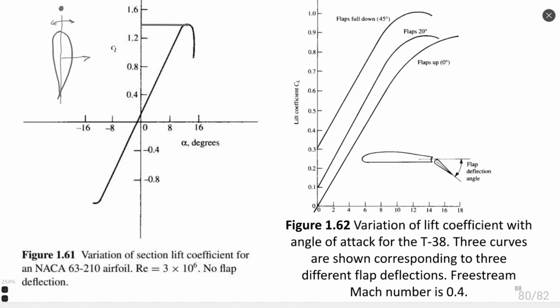And since we have this lift force, let's still call it lift force, normal to the fin, we still have a distance between the aerodynamic center and the center of mass. This force is created on the fin, because this airfoil is placed at the end of the rocket.